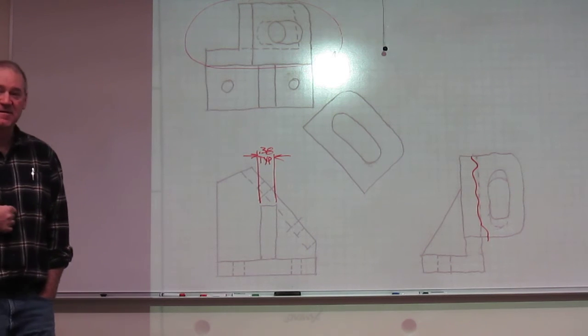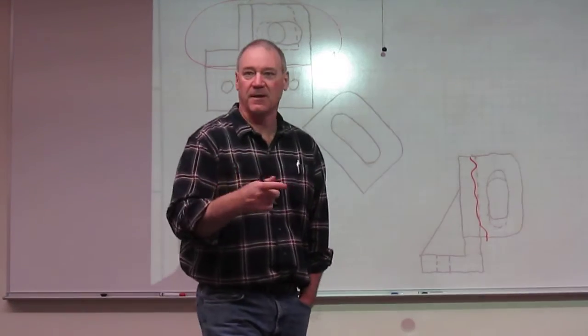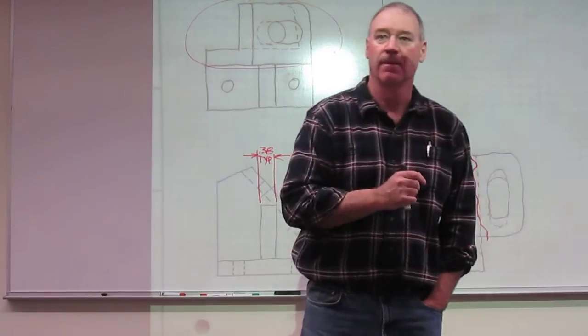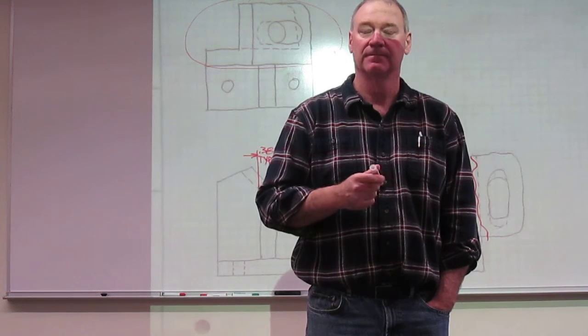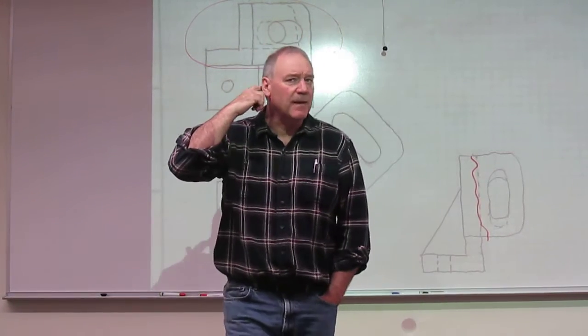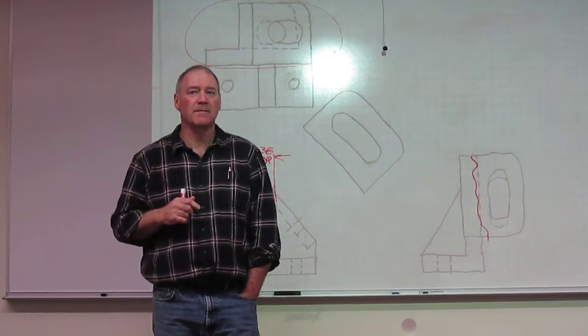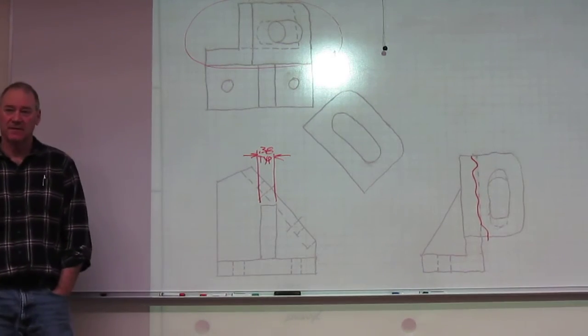Tolerance is the amount of slop any dimension can get. You're confusing the two. They aren't related at all. No, but if you have a tolerance on all dimensions, and then you have a typical, the typical would be 0.38. Are you saying if I'm using bilateral or limit dimensioning with it? Yeah. Okay, then it would be a comma, typical. But you still dimension it in full.